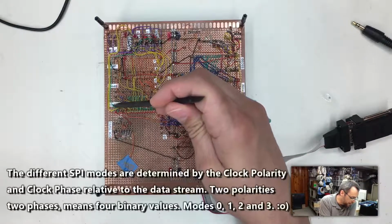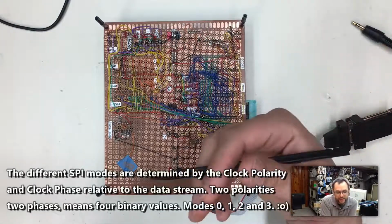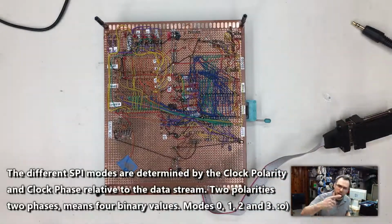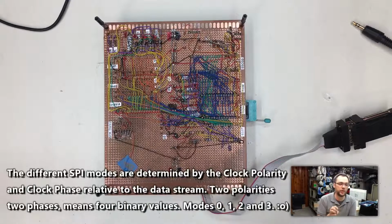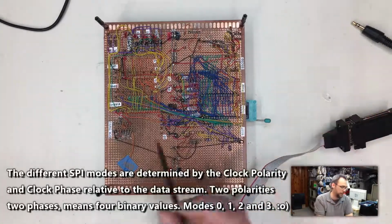Talking a little bit more about SPI mode 0 and 1, basically mode 0 says that the data has to become valid on the data bus before the clock comes high. But on the VIA chip, when it's in its standard clocked serial mode, the data becomes valid half a clock late.